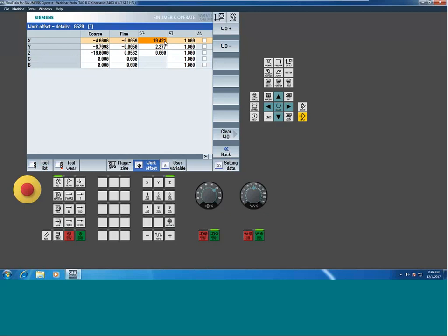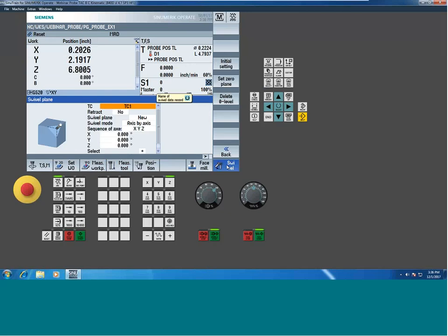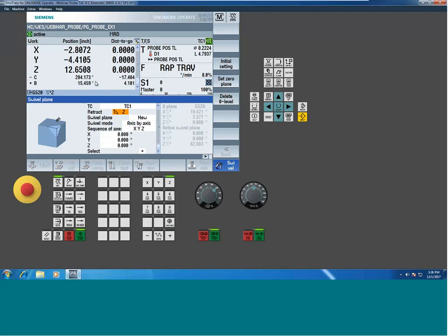So if I want to then send my 5-axis machine normal to that surface, I then drive the machine to that position using the swivel cycle. So a quick swivel cycle telling the machine to go to 0, 0, 0. I'm going to do a little retract action in my Z. Will initiate these two planes, and the machine will then calculate automatically for you where it would need to spin the B and the C to make that normal. So now I should be perpendicular to that surface.